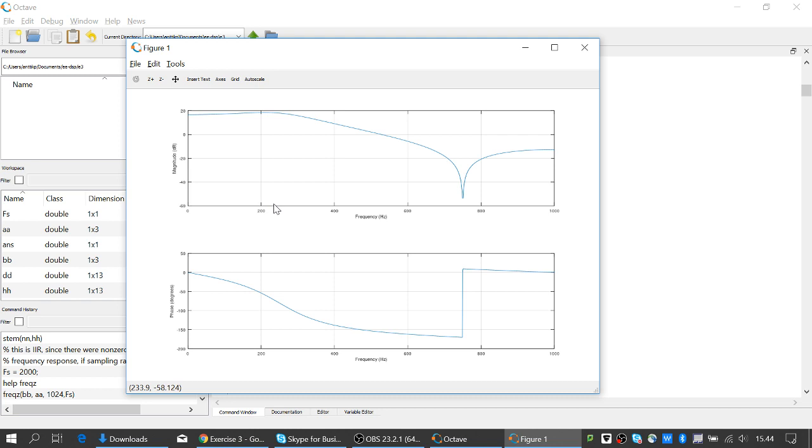Okay, and it also says, we had about, this is at 750 Hertz. Well, if this is 1000 Hertz, then 3/4 of that one is 750 Hertz, where the amplitude response goes to 0. And it looks more or less like that, quite similar, except this is on linear scale. I'm not good at drawing, on logarithmic scale. This 0 gives me some trouble.